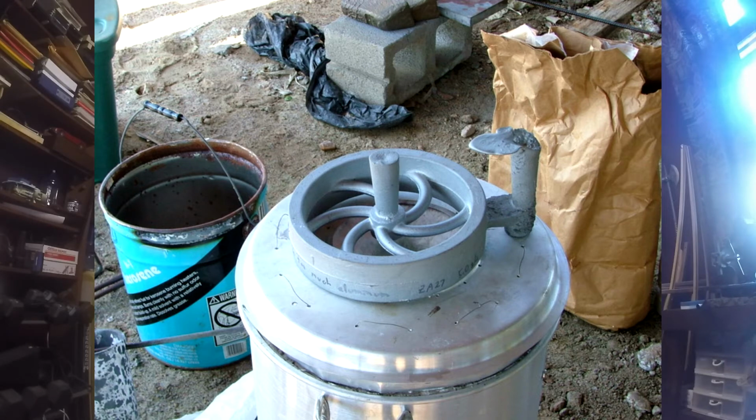Now that riser wasn't the right size. It was too small, and you can see that, but it did at least do a portion of its job. See how it's got the dip in the very top? That's called piping. That's a dip in the top of that riser where that portion collapsed as it was feeding everything down below.